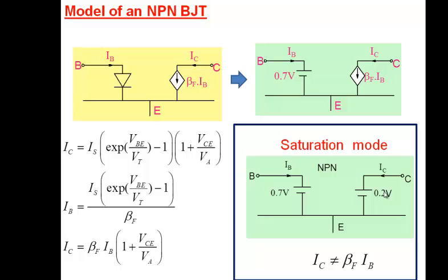Now, for the sake of discussion, for carrying out analysis, we take it as 0.2, but as I said, don't let it settle in your memory that everywhere I see a transistor, I should put 0.2. If you're doing a design, it's best to go and check the data sheet of a transistor from the manufacturer. From there, you can figure out what the appropriate value is. So for the sake of discussion in this course, we are taking 0.2 and 0.7. But otherwise, if you want to be more accurate, look at the data sheets. The manufacturer will give you what the appropriate values are.